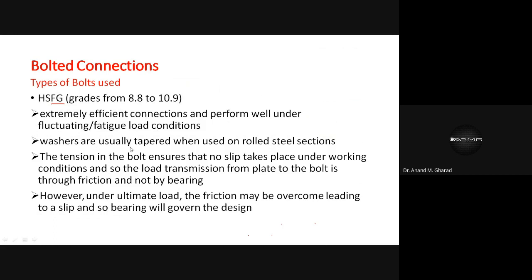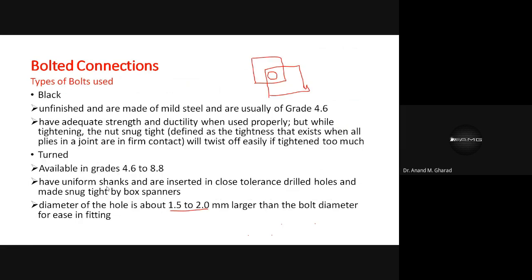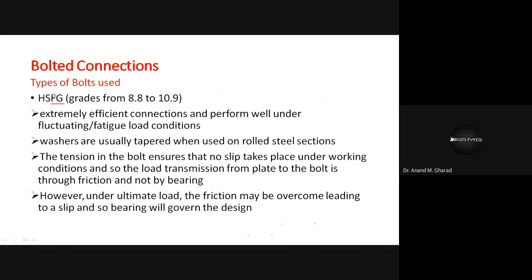The washers are usually tapered when used on rolled steel sections. The tension in the bolt ensures that no slip takes place under working conditions, and so the load transmission from plate to the bolt is through friction and not by bearing. So there is no such connection between the plate and the bolt. So you can see over here, there may be a chance that under the loading, the plates may get in contact with the bolts and the bearing action may take place. Okay, so such kind of possibility.